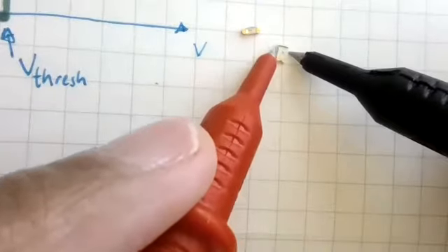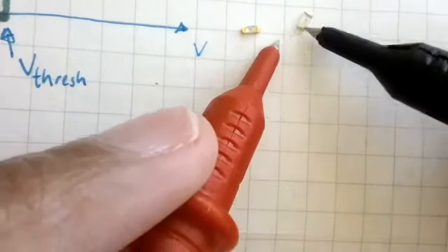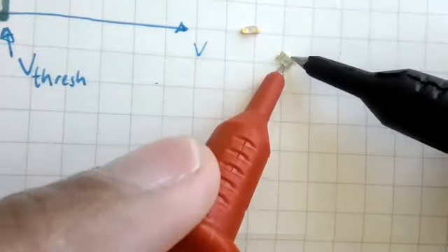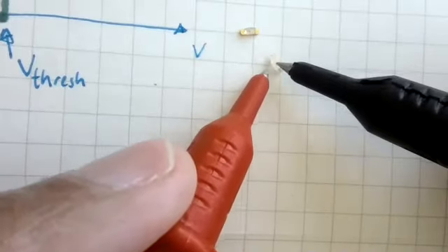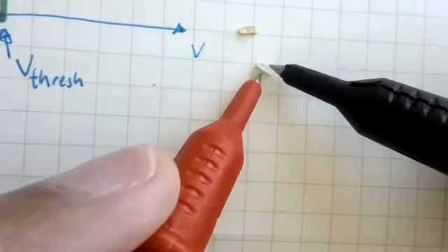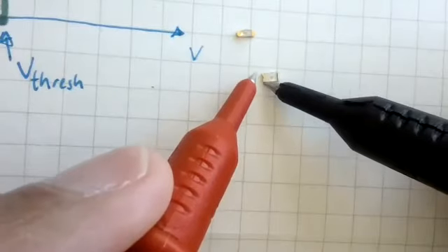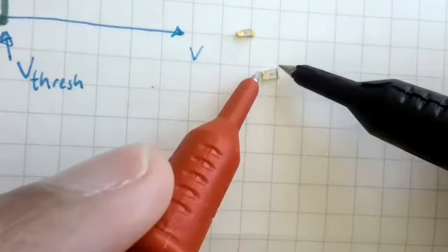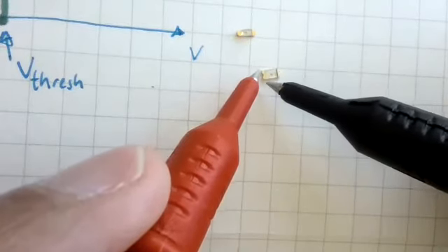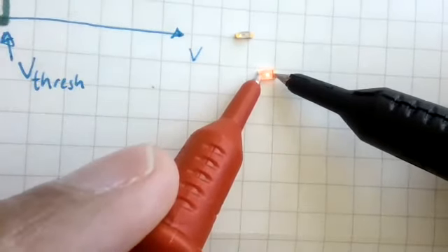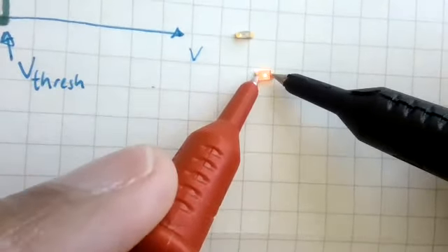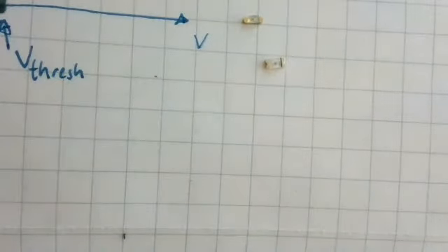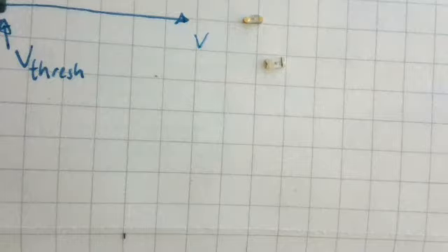So similarly, this is a 1206 LED, which is the kind that you guys are going to be using. This particular model doesn't have anything on the back, which, who knows? You don't really care about that anyway, because you're not putting it on the PCB in that direction. But you can see that there's a small line on this side that's not on this side. And so now if we line it up properly, then it lights up really nicely. So when you're placing these on the PCB, make sure that you figure out the proper orientation of your LED and then put it on properly.